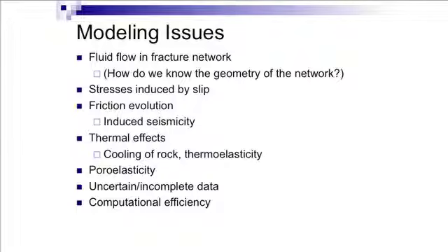So when you're putting water into the pore space of a rock, it actually can basically swell a little bit, and that changes the stress state. So these are things I have to worry about. Also, friction evolution. An earthquake is really a situation where friction weakens and then re-strengthens very rapidly on a fracture. So we actually have to model friction itself on the fractures.